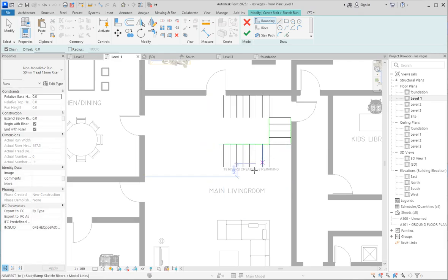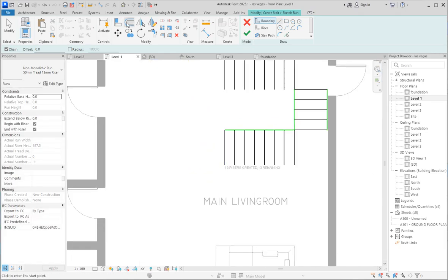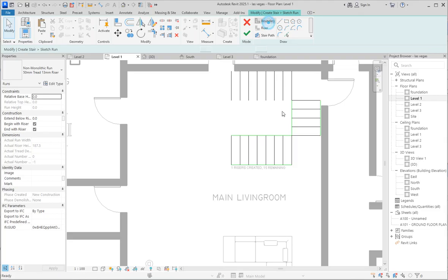So this one that has an issue with 1000, so just need to do what? Offset it by typing 1000. So offset this one. Wherever it stops, you use a trim extension to finish off the whole system. So select it, everything at once. It will close. So what do you need to do? Follow the boundary aspect again. Click and close it.